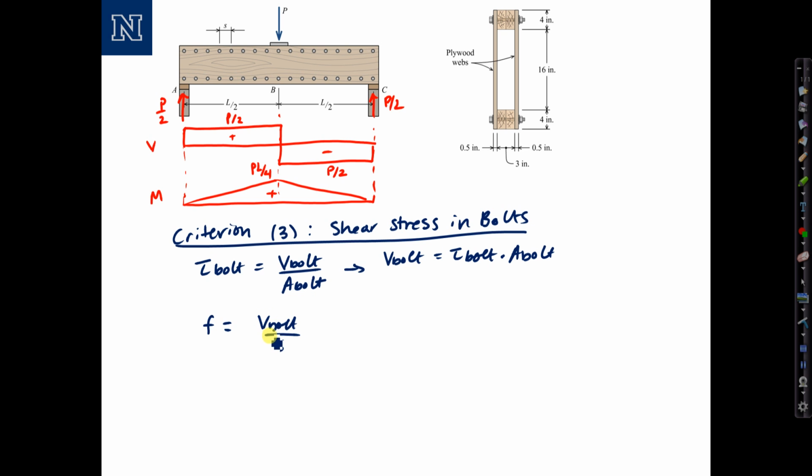And we're going to multiply that by 2 because we have 2 bolts across the connection interface, one on each side. So each of those can carry some of the shear. That doubles the amount of shear that can be carried. Let's write that as 2 tau bolt times A bolt divided by S. From a demand point of view, the shear flow is equal to VQ over I, which we'll rewrite as P over 2 times Q over I. So the point load P on the beam is going to cause a shear flow equal to this value.